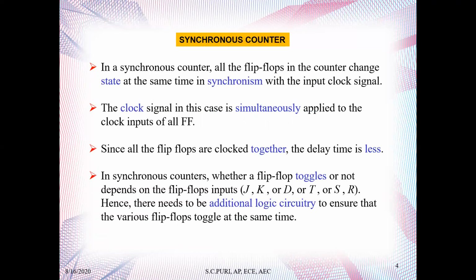In synchronous counters, whether the flip-flop toggles or not depends on the flip-flop inputs J, K or D or T or S, R. Hence there needs to be additional logic circuitry to ensure that the various flip-flops toggle at the same time.